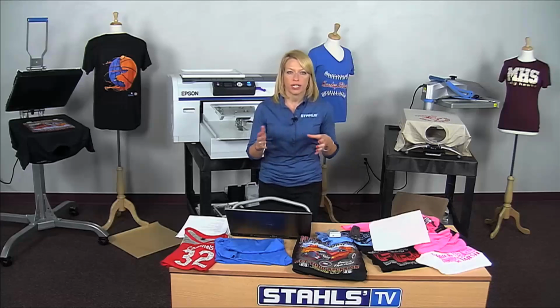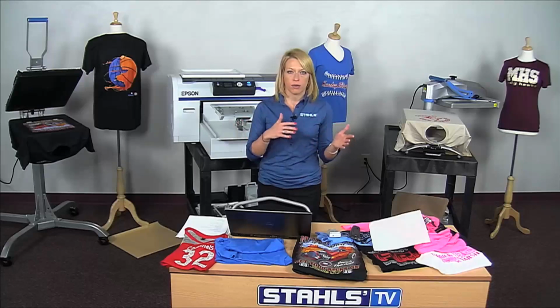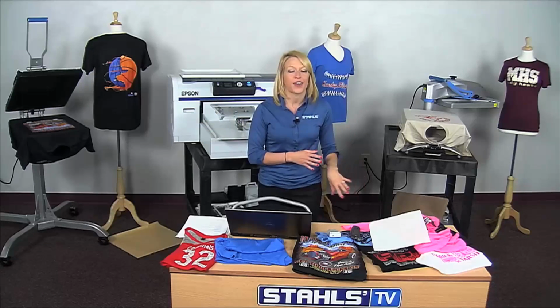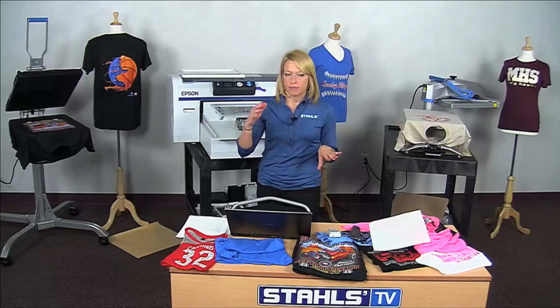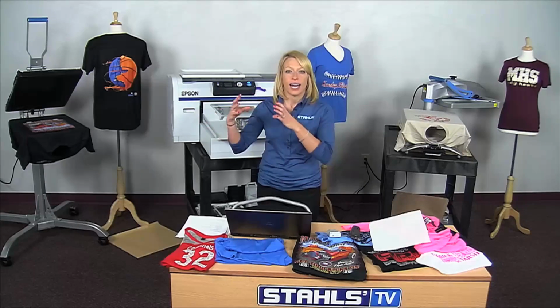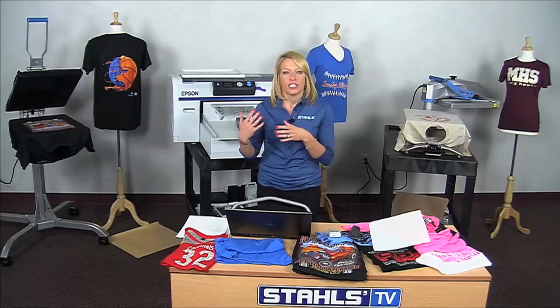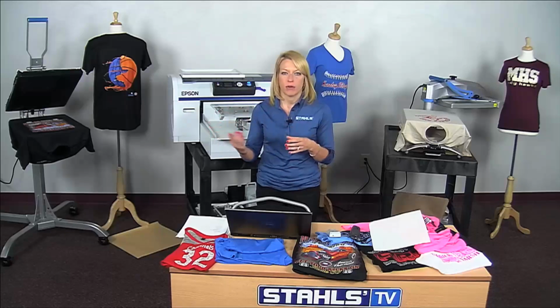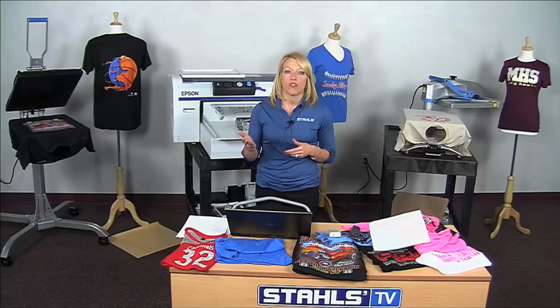The final way to print a t-shirt that I like to look at is the technology for when the job you have doesn't fit into any of the other technologies we've shown you today. This is the job that is very low quantity, very high color count, and maybe on a difficult to print item or a t-shirt that's 50-50 or 100% polyester, and that is what I call the digital transfer or the solvent ink transfer.